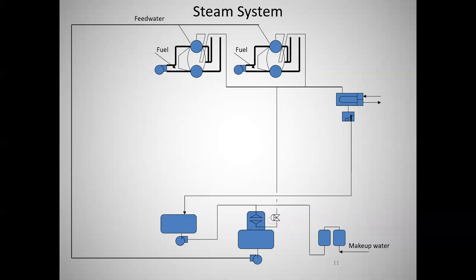Water tube boilers are what utilities will typically use to produce really high pressure steam for power generation. And I know it's a little hard to see, but these little circular tubes are meant to indicate the steam generating tubes. And when you come out of here, this one that goes down like that and back up is meant to indicate a superheater tube.